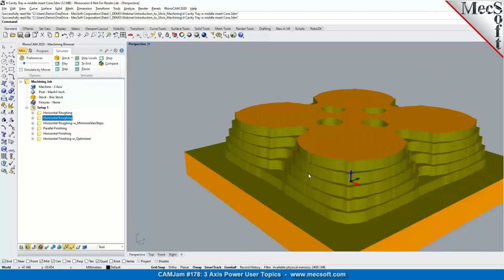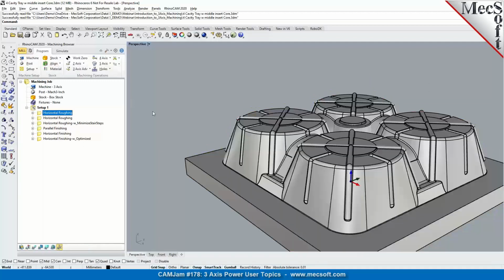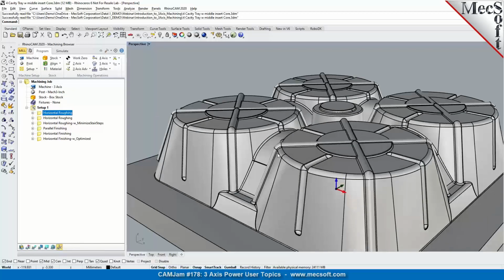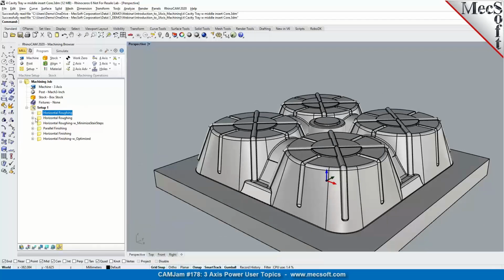The one that you're noticing here is with a slacker tolerance, and this one is with a much tighter tolerance. So, making the tolerance much smaller, tighter, will result in a higher accuracy finish, again, at the expense of more lines of code, and the computation time would also be longer for a tighter tolerance.